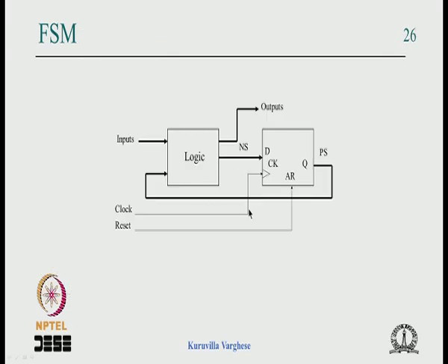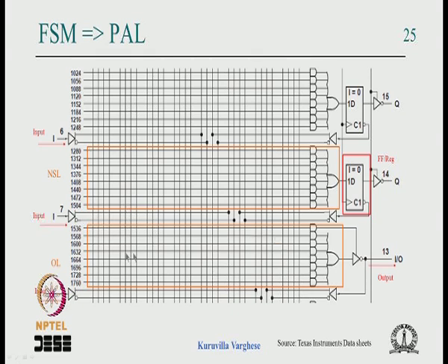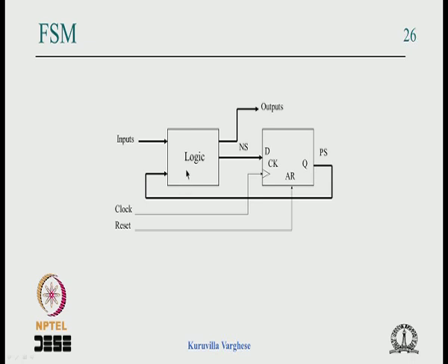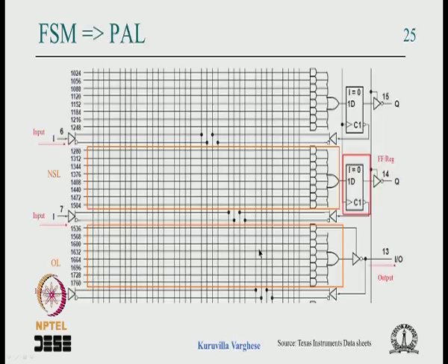If you view it like that, then instead of viewing the next state logic and output logic as separate, we can view it as a single logic where part of the logic is used for the next state decoding, part of the logic is used as output, and that shows you have a huge logic section. Some of it goes to the flip flop, some of it goes as output, and that is what is shown here. You have flip flops feeding back into an array, that array is logic which combines input and the present state, and some goes back to the flip flop, some goes to the output. Exactly the same thing. You have an array where input is available here, the feedback is available here, and some part is used as next state logic which goes to the flip flop, and some part is used as output logic which goes as a combination output. Exactly the same thing.